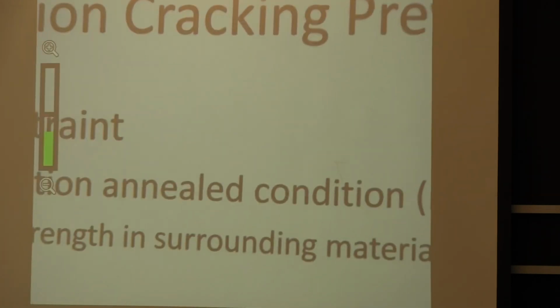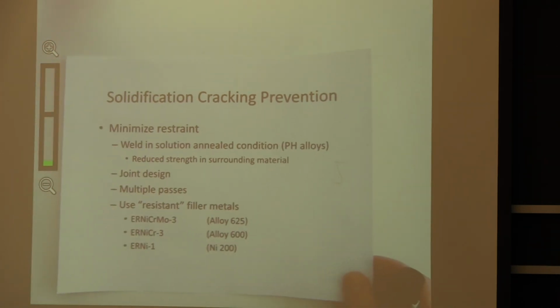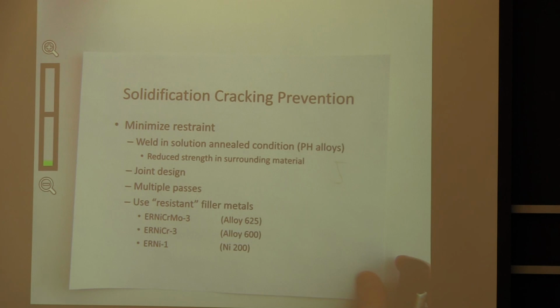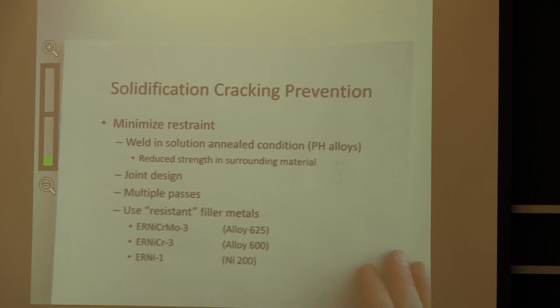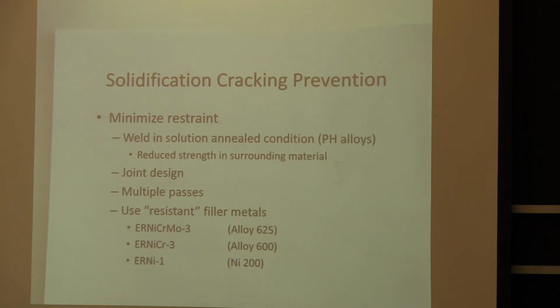So what can we do? What can we do to prevent solidification cracking? A big thing is if we can minimize the restraint in the material. As that material is solidifying, if it doesn't have stresses pulling it back apart, then it's not going to crack. And so we want to minimize that restraint as much as possible, and there are various